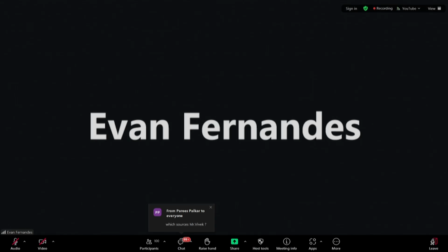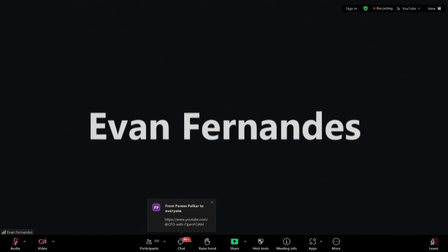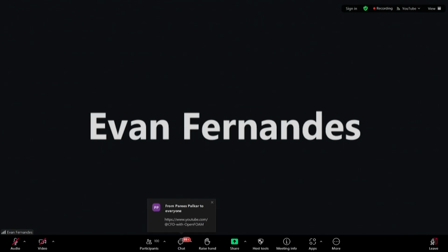Because if it is giving you an error at the very last step, that is, in ParaView when you're opening it and trying to load the case, it gives you some error in red, right? In one box down. Yes, sir. So that is most probably because some file is missing, like you have either given a wrong boundary condition or some of the things are interfering with each other. But then that should always give you an error at the very beginning, when you are solving your simulation, in your terminal.